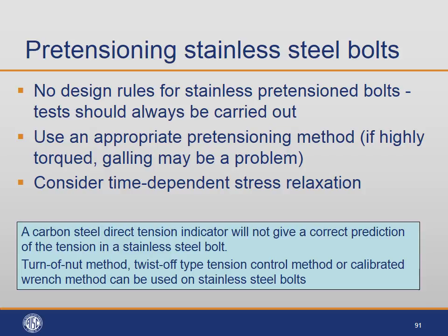Now currently there are no design rules for stainless pre-tensioned bolts. So what I've said before has been for bolts that are the bearing type of connections. And for this reason you should carry out tests. They are used in structures around the world, but in order to validate the strength from them and the correct pre-tensioning procedures, you should carry out tests.